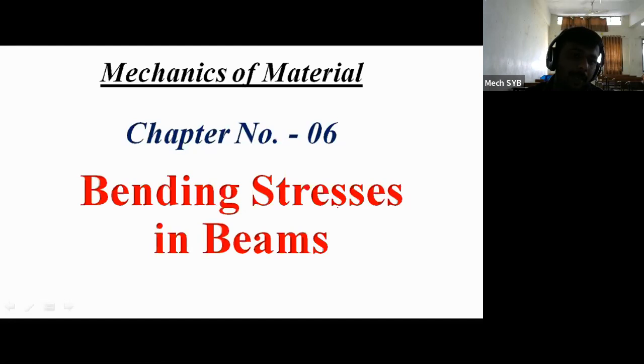By using the bending moment value, we have to calculate one stress, and that stress is called as a bending stress. Please keep in mind, if your beam is subjected to the bending moment, then same beam is also subjected to the bending stress also. And in addition to that, if your beam is subjected to the shear force, at the same time in the same beam some amount of shear stress is also induced. And now we have to calculate that stress value.